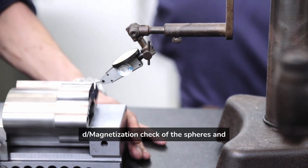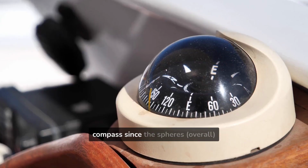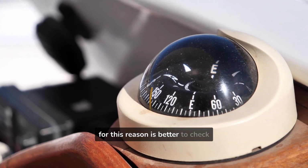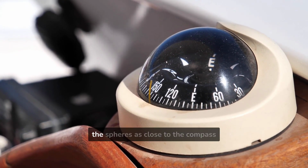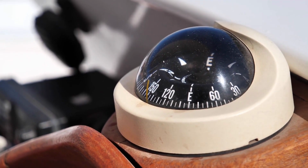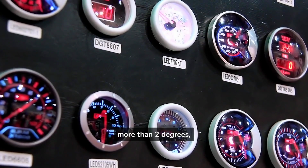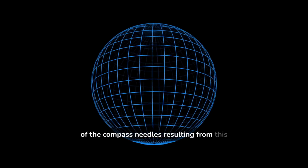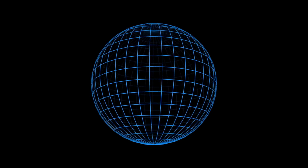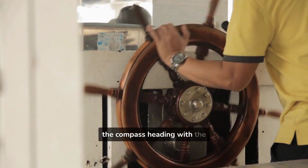D/ Magnetization check of the spheres and Flinders bar. Sometimes it is difficult to adjust the compass since the spheres, overall, are magnetized. For this reason, it's better to check this possibility, i.e. move the spheres as close to the compass as possible and slowly rotate each sphere separately. Any appreciable deflection, more than 2 degrees, of the compass needles resulting from this rotation means that the spheres have residual magnetism.